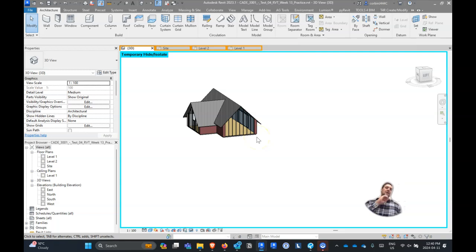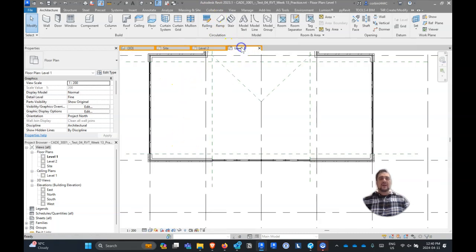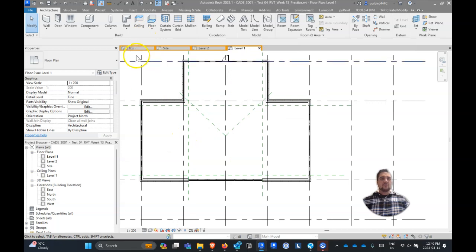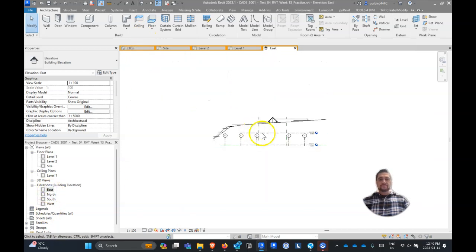And I think the one last thing I'm going to do with this building per se is add foundation walls around it. And I think this is something that you can do with a lot of your projects, even your commercial building, by adding that trench wall kind of around your building. It looks like your building is touching the ground. And so that's one common thing I see with a lot of people just starting to work with Revit and design. It's like having some sort of foundation, something that's grounding it to the ground, is just a nice visual piece that helps. So let's go to our elevation here.